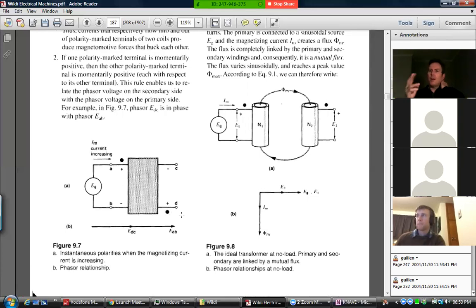We often do show a current direction in these things, even though it's always changing. It's just that it gives you some reference. So on a phasor diagram, when you see a voltage at a certain time t equals 0, and it crosses that zero axis, at that instance you have a vector a certain way, a voltage a certain way, a current a certain way, other currents relative to that, just so we can see at an instant how the things relate to each other. But yes, 10 milliseconds later, everything changes.